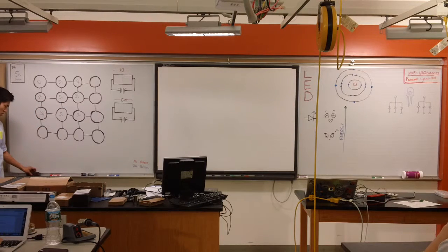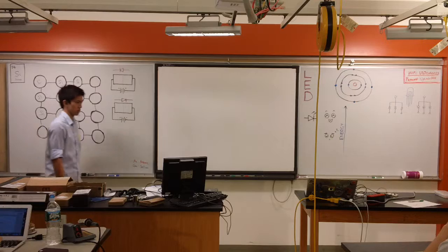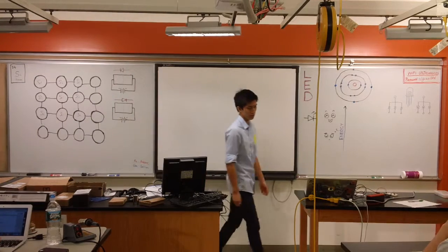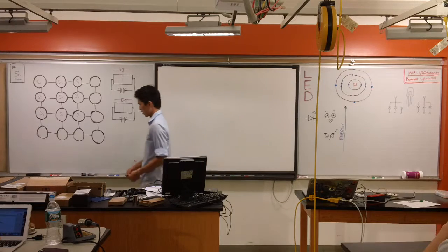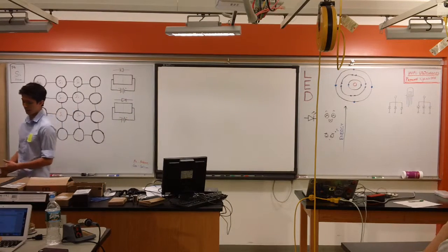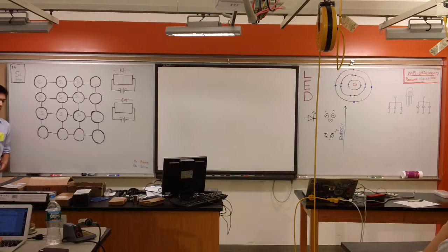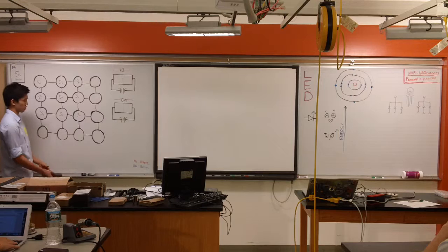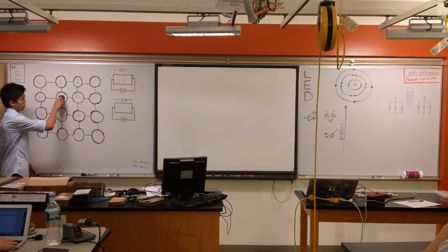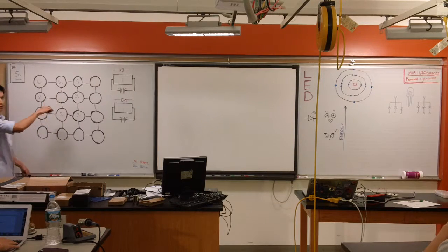So the way you make silicon conduct electricity is, you have to dope it. And it's kind of a funny word, dope, but what it means is to introduce impurities into the silicon crystal. And there are a couple of different ways of doing that, but essentially what they're effectively doing is swapping out one atom for a different atom every once in a while.